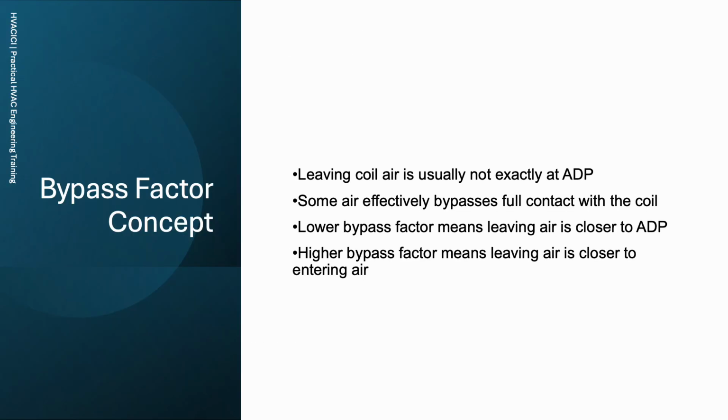In practical equipment, the leaving air usually does not reach ADP exactly. It falls somewhere between entering air and ADP. The bypass factor describes how close the leaving air condition gets to the ADP condition.